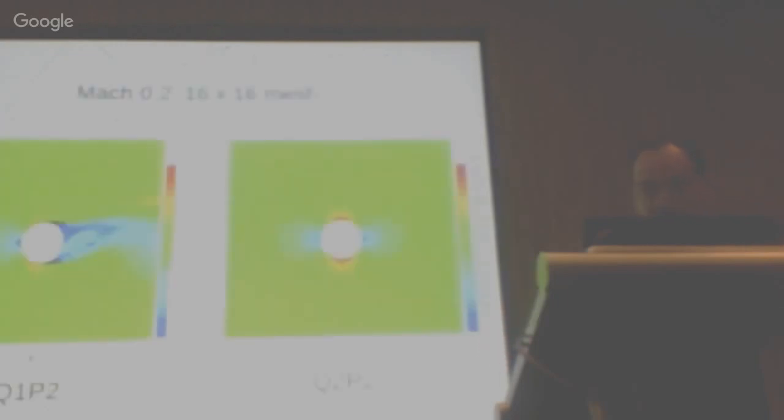So for the linear mesh, the edge is quite visible, different from the geometry, and for the high order one, you see that it projects much better. And so a little bit of nomenclature here. Q1 stands for a linear mesh, first order degree mesh, with a second degree polynomial for the flux reconstruction solution. So it's a third order scheme using a first order mesh, a mesh with straight edges. And this other one is the same third order spectral difference scheme, however using a quadratic mesh, the one I showed on the previous slide that is curved along the edges of the boundary.